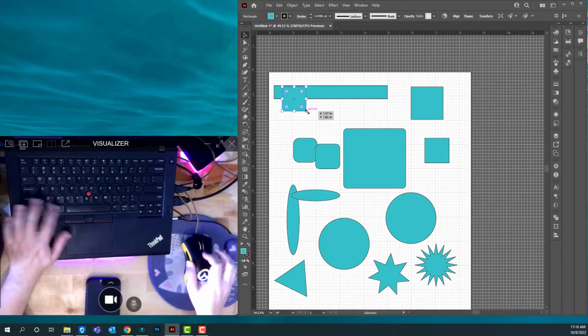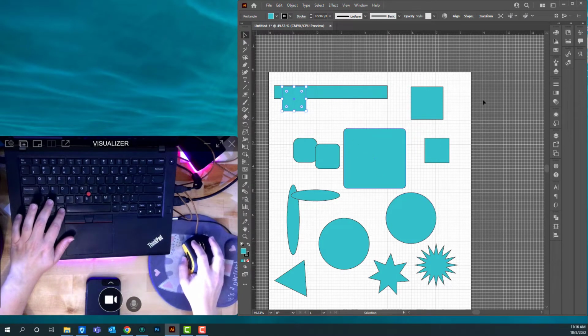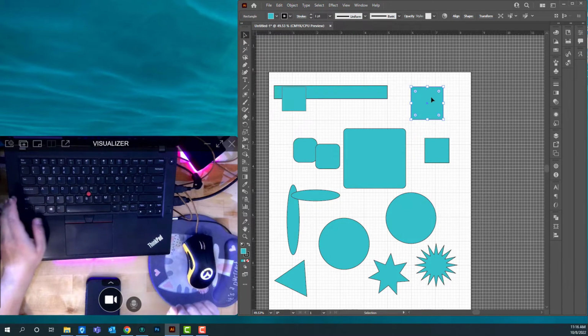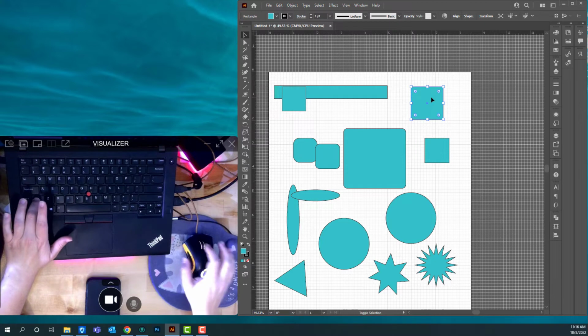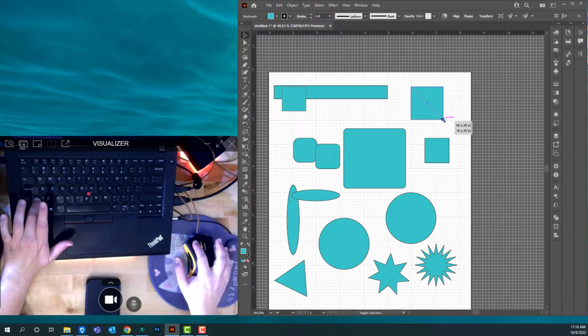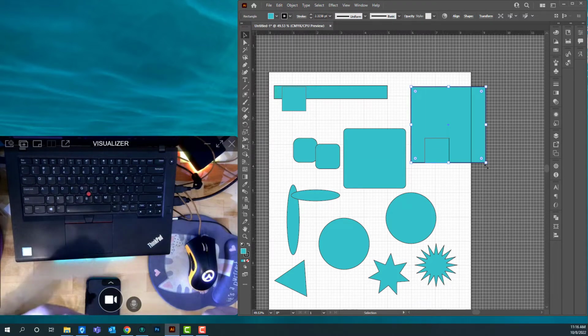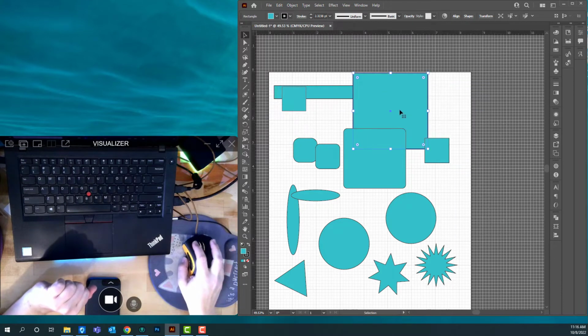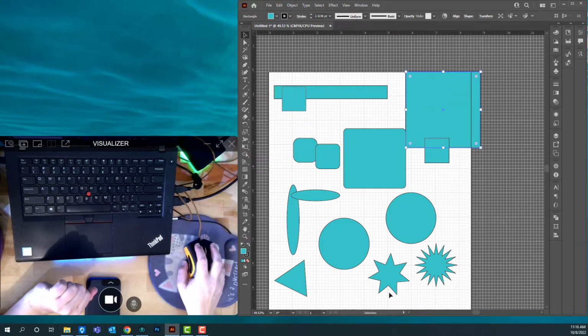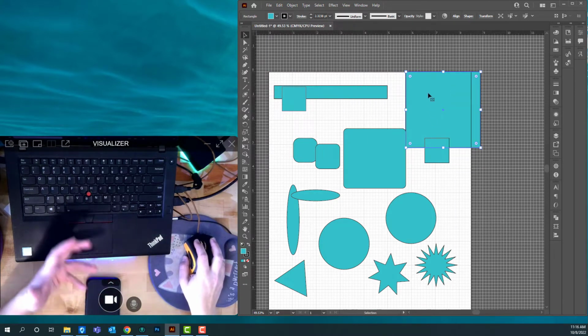Same thing happens when you use keyboard shortcuts with this. So I'm going to select this square. If I want to keep this square perfectly proportioned, I'm going to hold down the Shift key. I'm going to hover over the corner where you see the two-headed arrow. I'm pressing down the mouse button, and I've got my Shift key down and my mouse down, and then I pull. I release the mouse and release the Shift, and I have proportionally resized my rectangle. So I should say square.